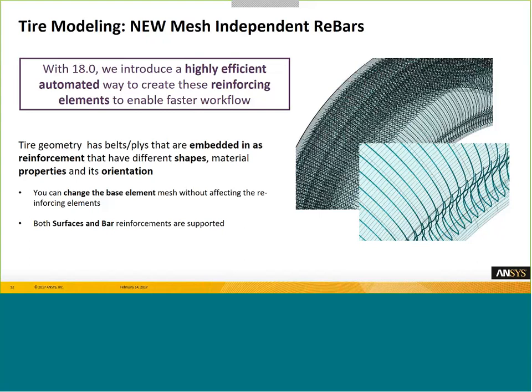They can have different shapes, material properties, orientations, etc. This happens automatically. We can change the mesh of the tire without having to remesh or reconfigure all the reinforcements. So it's a really, really quick way, a really, really accurate way of modeling these reinforcements